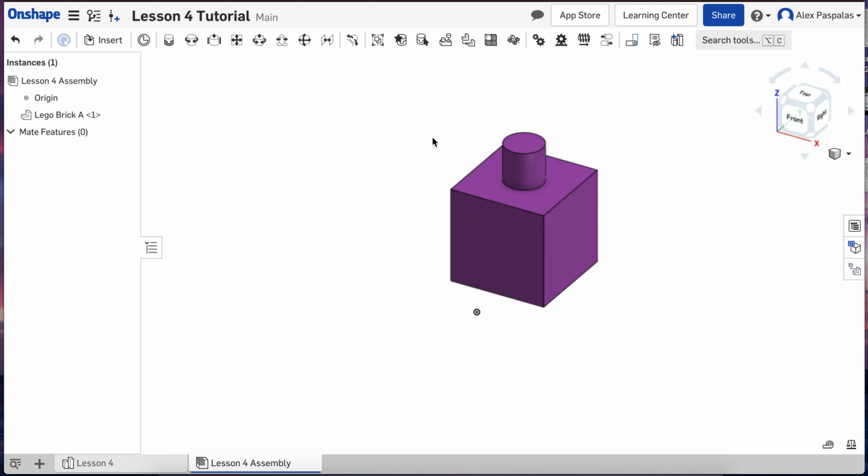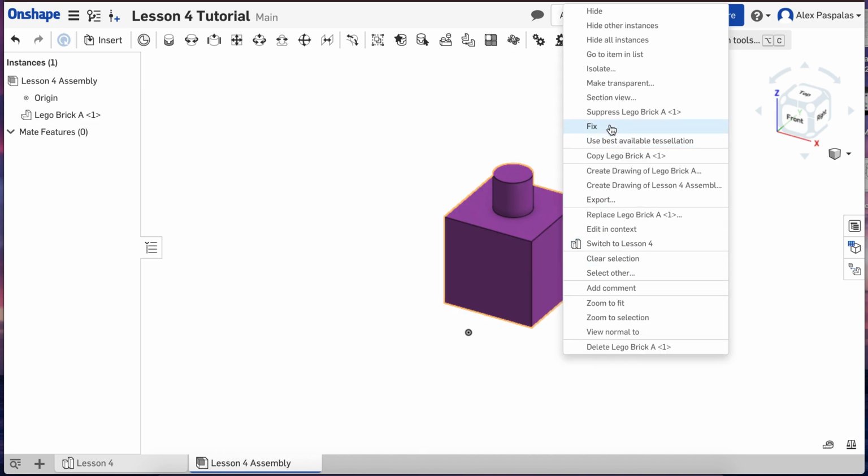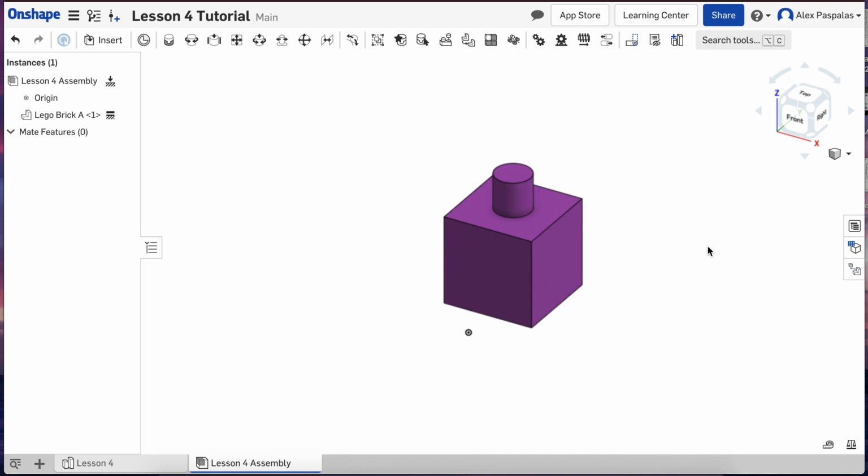we can choose to fix the part down to where it is positioned in the workspace. You always want the first part you bring in to be fixed. That just helps, when you're moving a bunch of parts, you never get out of square. And this will make more sense once we start engineering drawing. So I'm going to 2-finger click on the part, or control click, and press fix. And now if I try to move this for any reason, I can't move it. And you see that this symbol comes up to say that the part is fixed. And that's what I want.